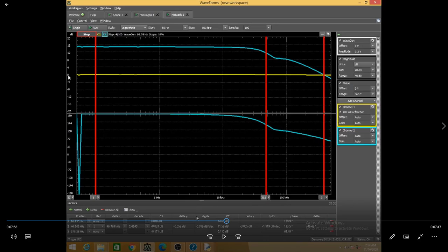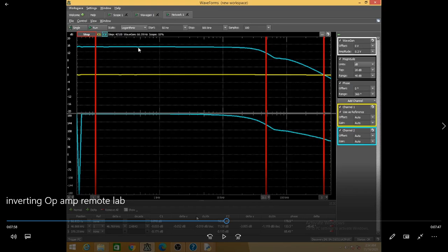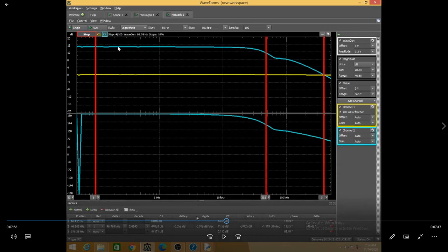No. Here in this case, what is the gain? It is 14 dB. Am I correct? Yes, sir. So is the gain keep reducing? Yes, sir, keeps reducing. At some frequency, gain will become 1. 0 dB is 1, because 1 is volt per volt.